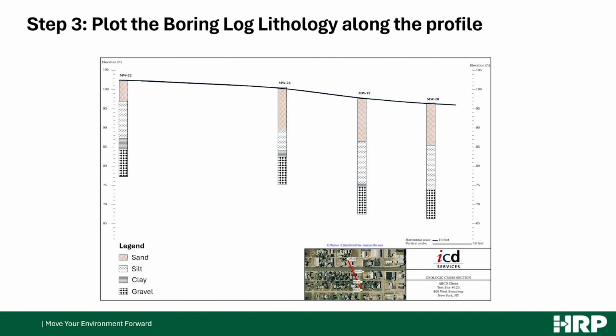Once you have your sample locations and your sample depths, you can then take your boring logs and make visual representations of the lithology in place within the line of section. This allows you to start to see how these layers interact with each other over this distance. Several geologic laws apply, such as the law of horizontality, where sediment will probably be deposited in flat horizontal layers. Also, laterally continuous layers, meaning that these deposits are large, and so you expect to see similar sediments within a short distance from each other in your site investigations if there isn't a tremendous amount of heterogeneity.